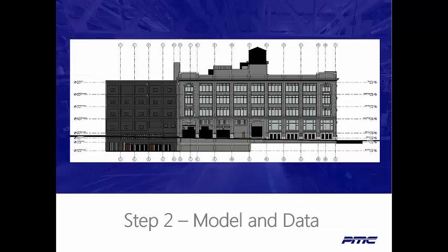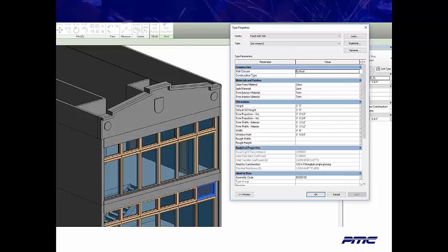Although point clouds can be integrated into most modern facility management systems, you will almost always need a BIM or Revit model as well. Having the BIM will allow data to be attached to individual objects such as doors, walls, air units, and other fixtures and devices. This is a sample from a Revit model. By clicking on this small window, which is outlined in blue, the properties of that element are displayed in a pop-up window. These include dimensions, manufacturer, finishes, etc. This data can also include asset management information, such as projected replacement date or date last serviced.